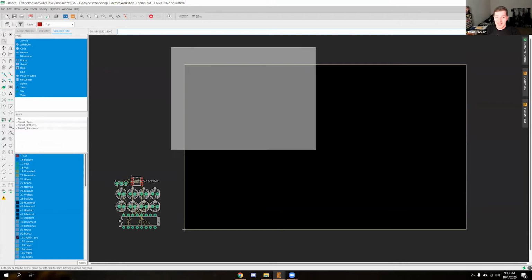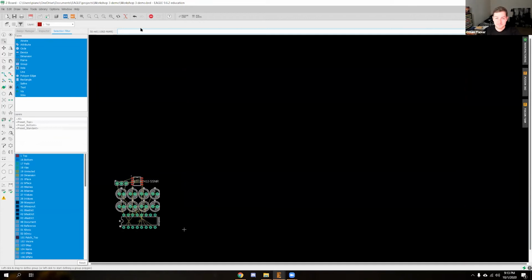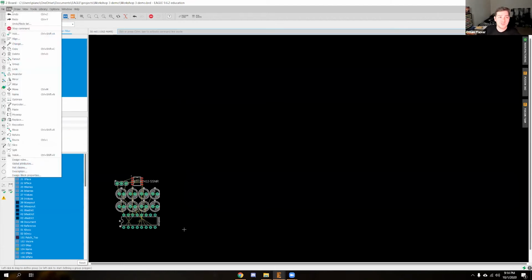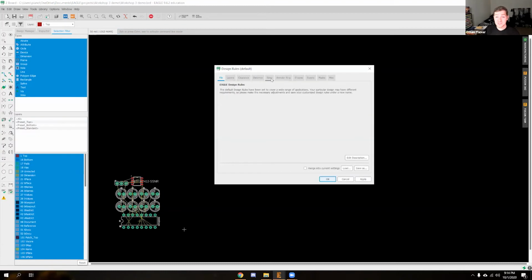So this is actually way, way, way too big for what we're going to be working with. Go ahead and just click and drag to select this whole entire thing. And you can hit delete. This is where the fun part comes in. We're going to set up a couple of tools and options. So go ahead up to edit here. And then go down to design rules. Go to sizes.